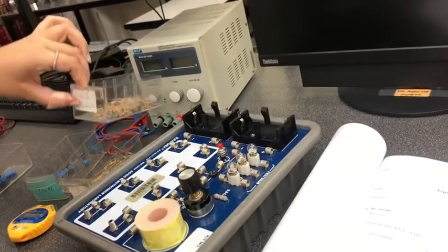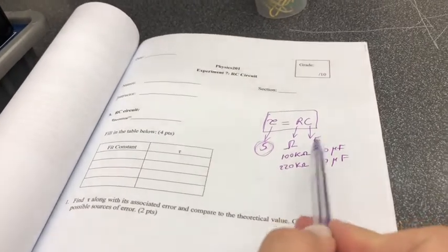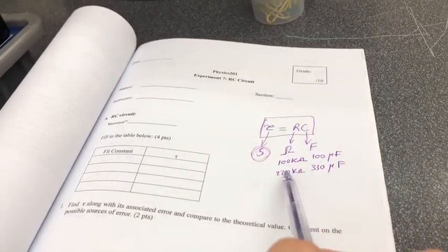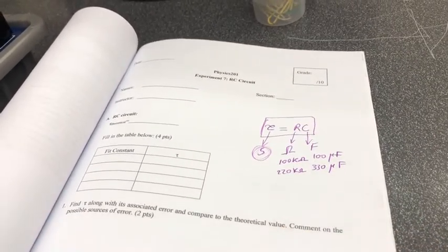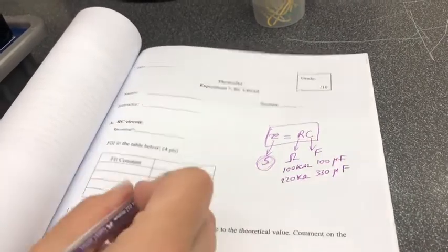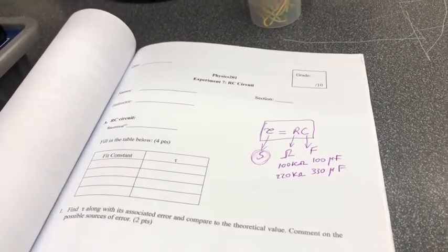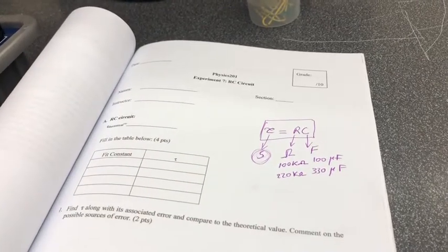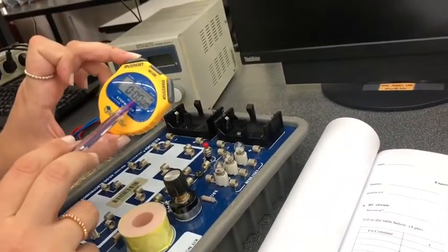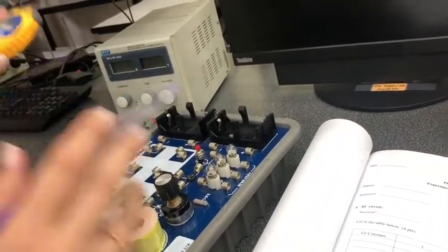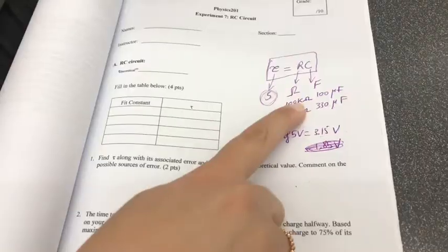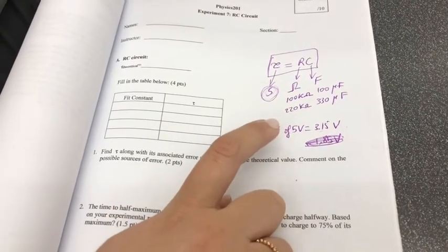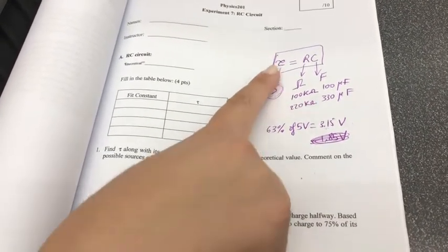Now we will make a circuit, for example, with the first resistor and the first capacitor, then the first with the second, and so on for each combination, and each time you have to find the tau theoretically using the formula. Then we will try to measure the time using a chronometer experimentally, to see how much time it needs to fully discharge or fully charge. Say it comes out to 10 seconds, that is 10 seconds for 1 tau.